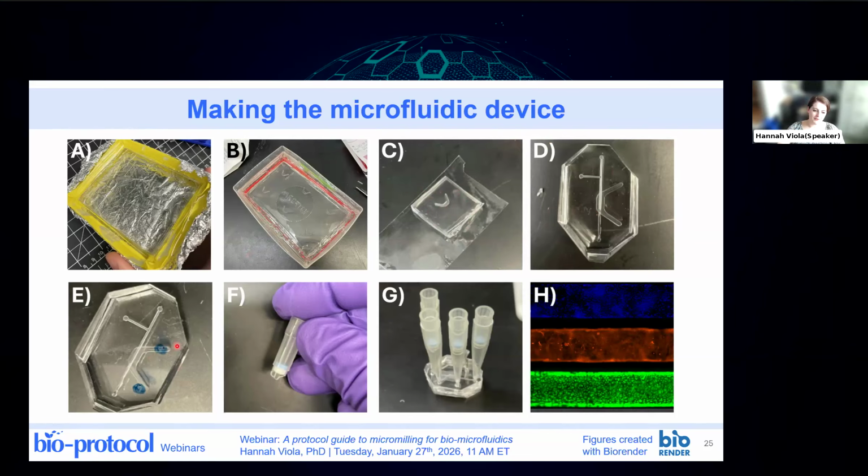And then before I learned about guide indicators, I was just putting a dot on the top mold, because you have to punch the hole through the top mold so that you can access the bottom channel. You can either do that by putting actual indicators in your design, which I have in the design that's published, with little dots here and little dots here so that I know where to biopsy punch, or you can also just put them together and then draw the dots. Then you need to use a biopsy punch, which is a little tool that cuts a circle.